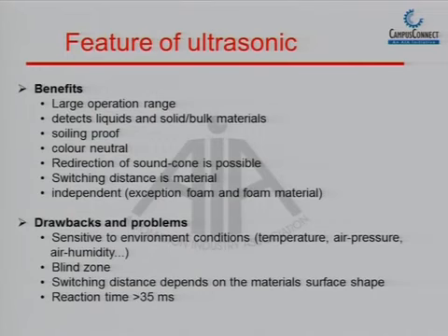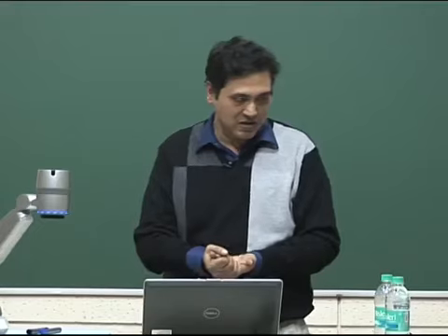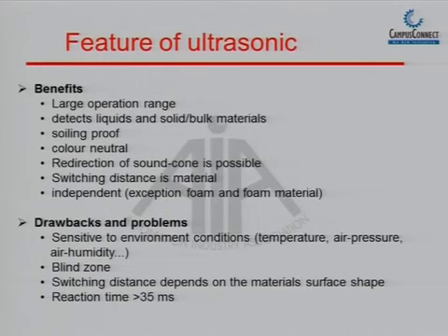Then soiling proof, that means the sensing head of the sensor will not get damaged easily, because the sound waves keep cleaning the sensing face, that means dust will not accumulate on the head of the sensor. Then these are some of the benefits, right.